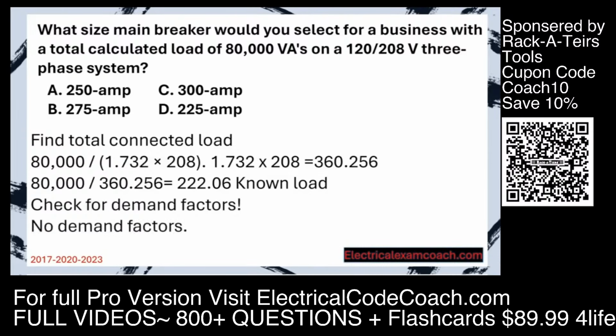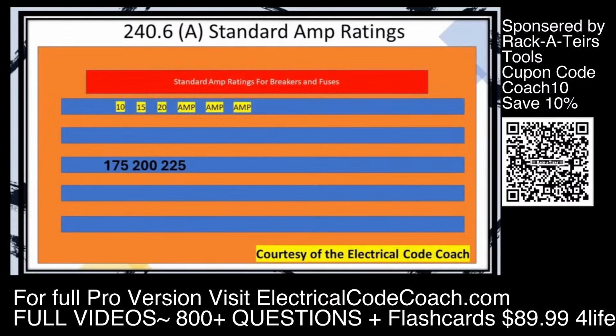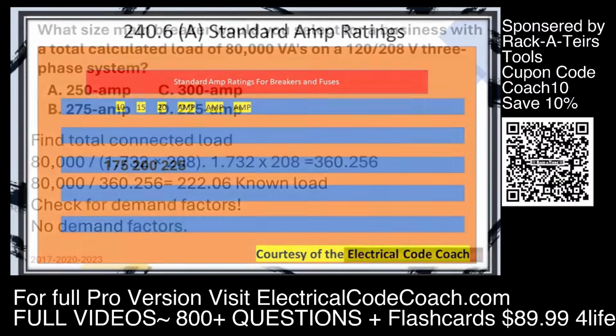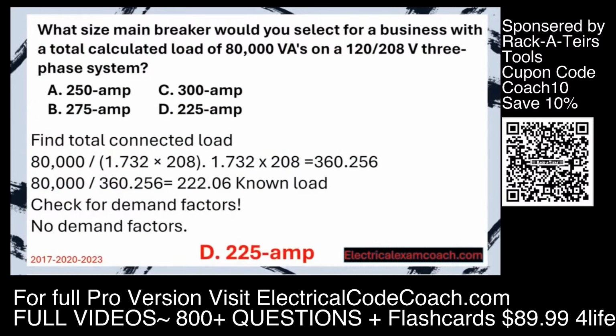There are no more demand factors in this calculation. We head over to table 240.6(A), choose the next standard size up, and put this on a 225 amp service.